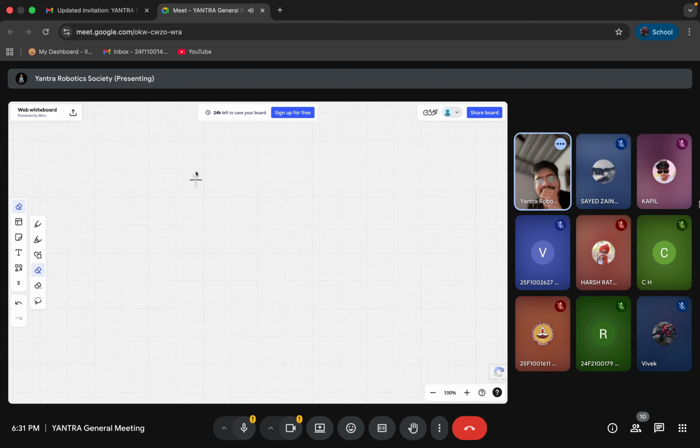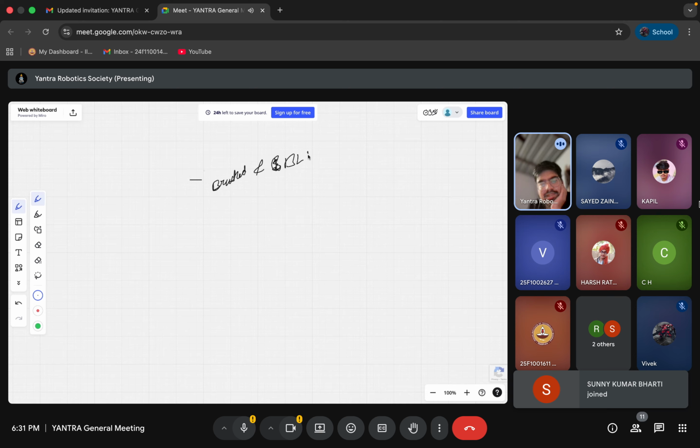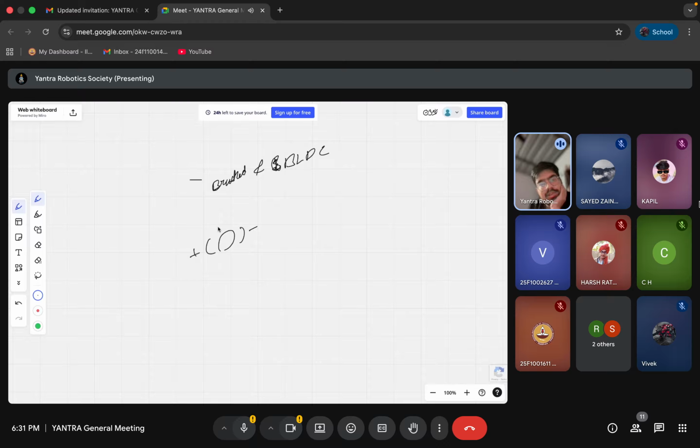So there are basically brushed and BLDC. In a brushed DC motor there are only two terminals, positive and negative, and you swap these and the direction changes this way or that way. DC motors are simple. These are mostly called coreless motors, but they are still brushed DC motors. They have only two wires, as you can see, one and two, simple.